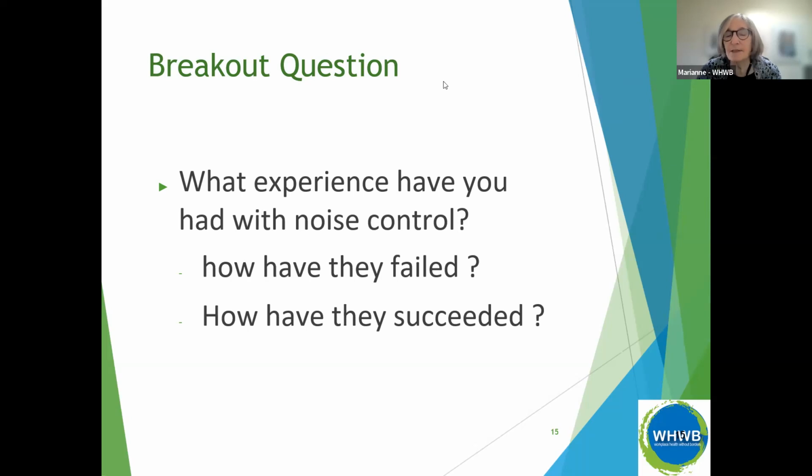Thanks. The other thing too is you may have a type of sound level meter or noise dosimeter where you have two separate meters on it. The more sophisticated ones have that, and you can do a setting so that one of them is measuring dBA and one of them is measuring dBC. That's very useful for this, if you have a sound level meter or noise dosimeter that will do that. It's helpful.